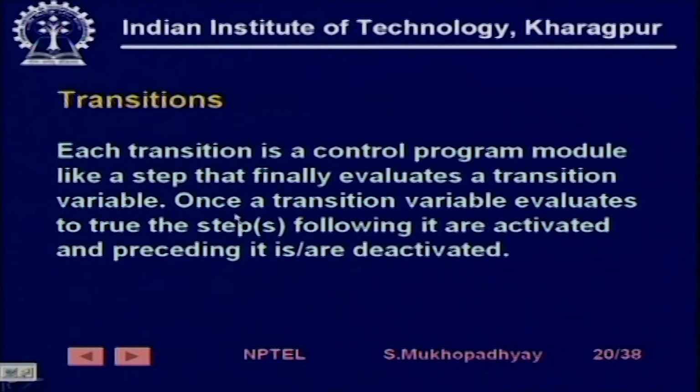And we say steps because in this formalism typically one transition can go to only one step, provided you do not have concurrency. But since SFCs support concurrency, it may happen that after one transition two concurrent threads of execution will start. So, that is why we have said steps following it are activated and those preceding it are deactivated.